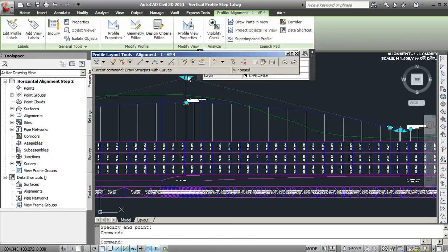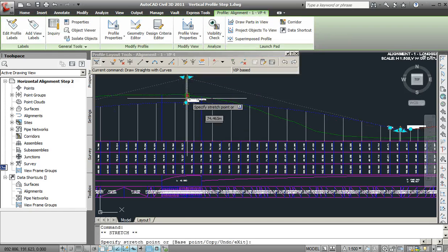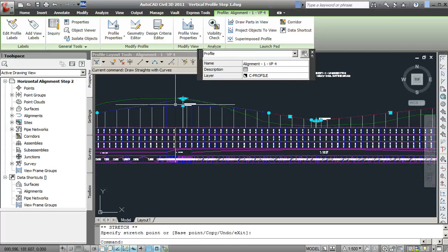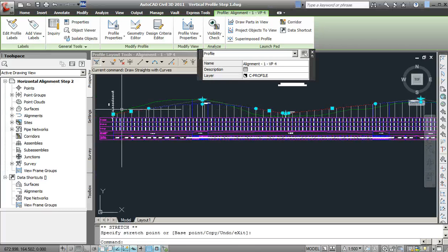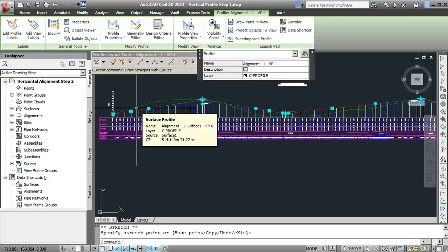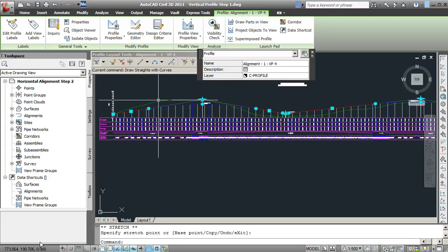If we click on the curve, the grips come up and we can make amendments to our drawing as before. This will have the result of changing the curve length and changing the gradients coming into the curve along the way. This process can be repeated until you have a design that complies with design standards.